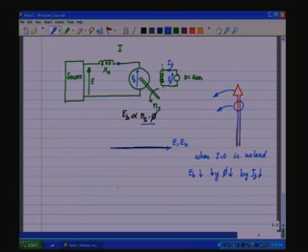So what will happen under such a condition? We have E, and EB is going to be lesser than E. And now what is the drop across the synchronous reactance? It is E minus EB.